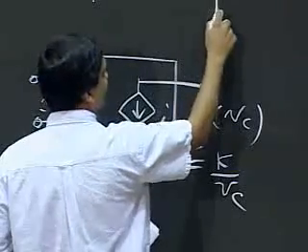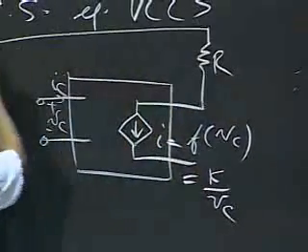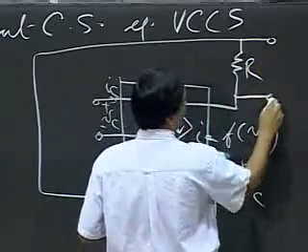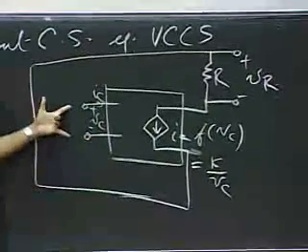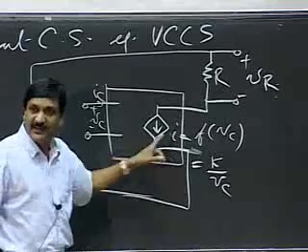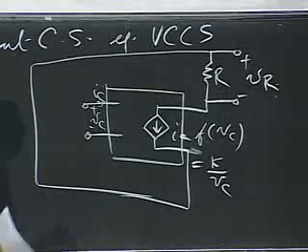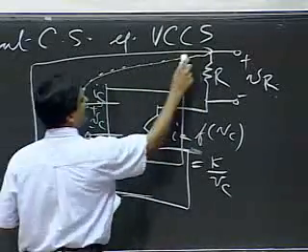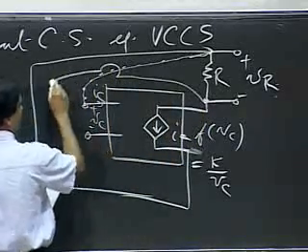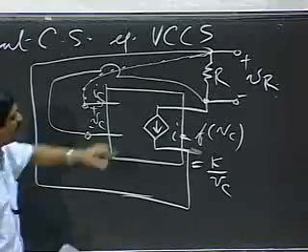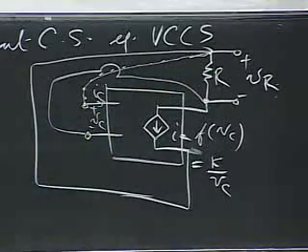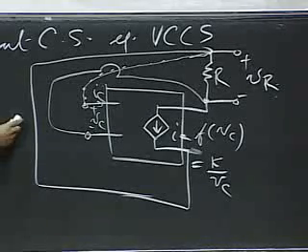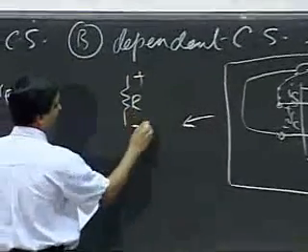So let me build a circuit of the following form. So let's say I have a resistor R, and here's my circuit. And as before, let me look to figuring out what VR is. Now notice that I have to supply some voltage at the input so that the output can depend on the input, because right now, I don't know what the input is. So what I'll do is apply VR over here. Let me make the connection from here to here. What I've done is I've applied VR at the control port of the dependent current source. And I often draw a circuit like this. This looks pretty messy. I will often draw the circuit like so. R, VR.